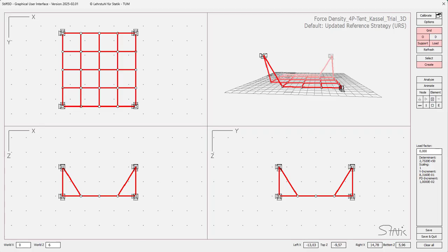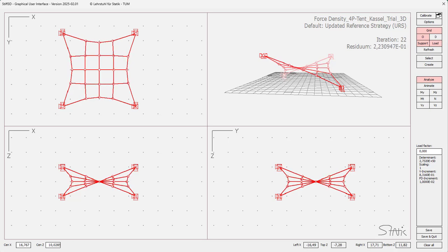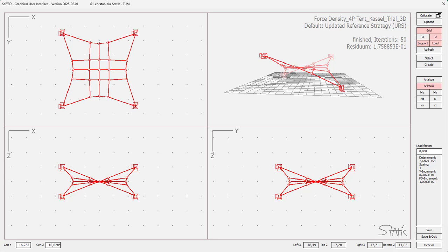As a convincing example where we can apply length constraints on cable elements, let's consider this example which we have done already before, about this three-dimensional minimal path cable net, where we just observed that there don't really exist solutions, and because of that cables just fall together. And to avoid that, quite obviously it makes sense to apply length constraints, for instance here on the elements of the edge cables. Let's try to do that.